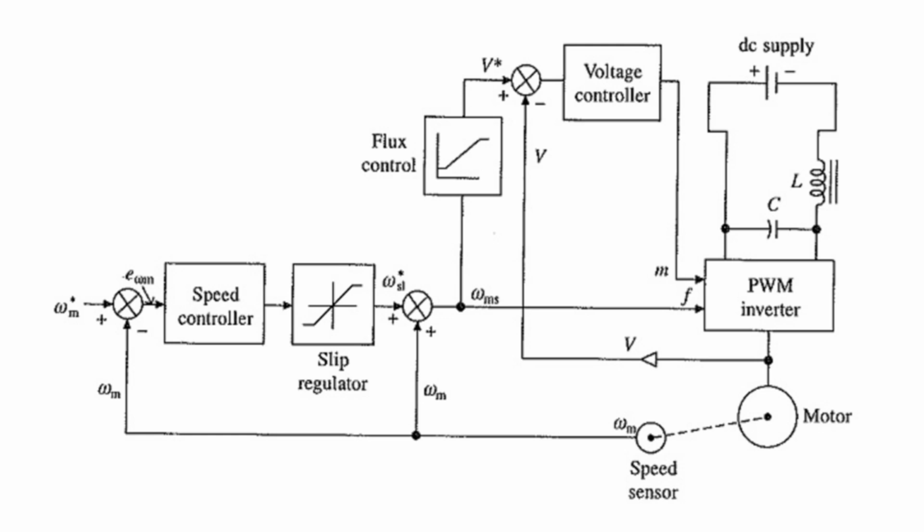If you consider how this circuit operates, generally you see the PWM inverter, which may be a VSI fed inverter or a cycloconverter. Both will be benefited for regenerative braking as well as 4-quadrant operation. This PWM inverter is fed from a DC supply through the LC filter used here.